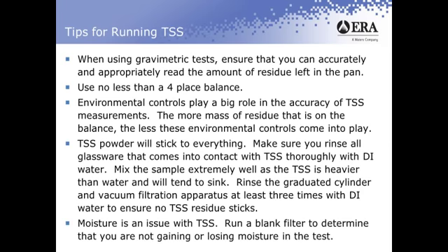Another major issue, again, as I had mentioned with TSS, is moisture. So what I'd recommend you do is to run a blank filter to determine whether you are gaining or losing moisture in your test. Very rarely when you run that blank filter does your residue on the blank filter actually show 0.0000 on your balance. It might show a small negative number, maybe 0.0002 or 3, or a positive number to that effect.